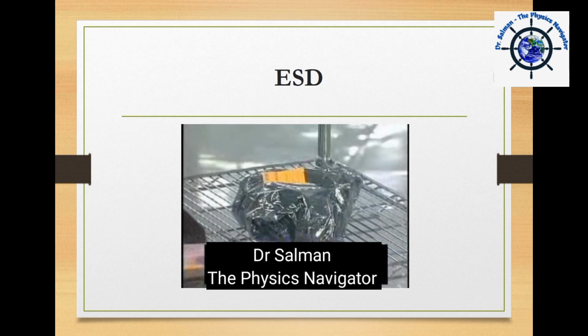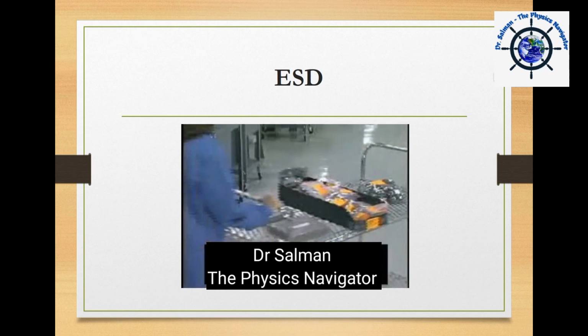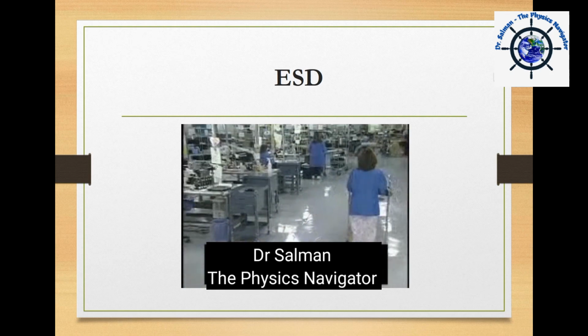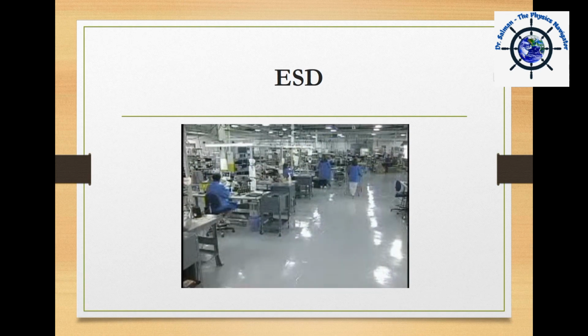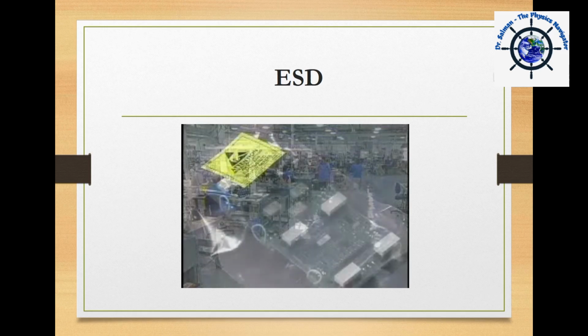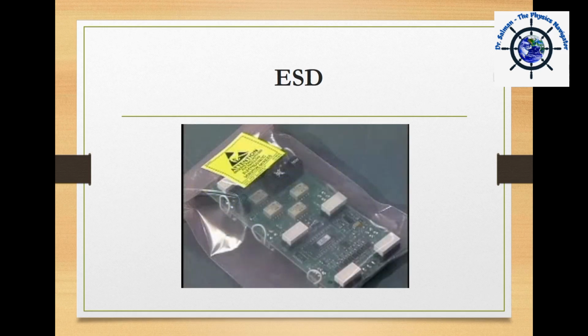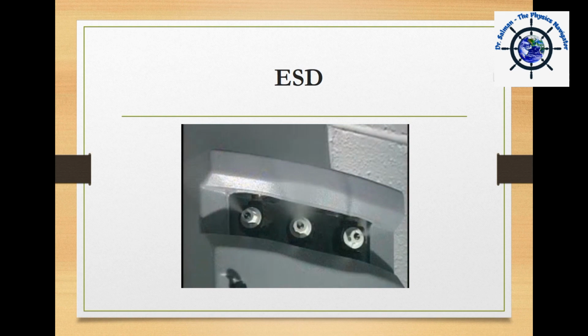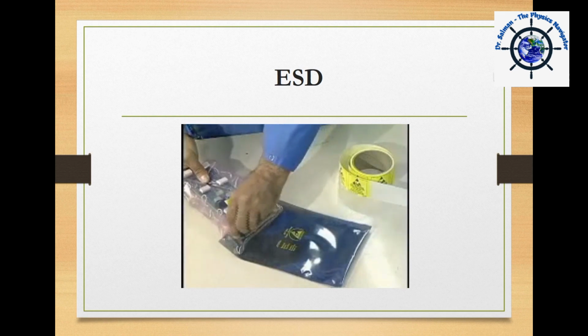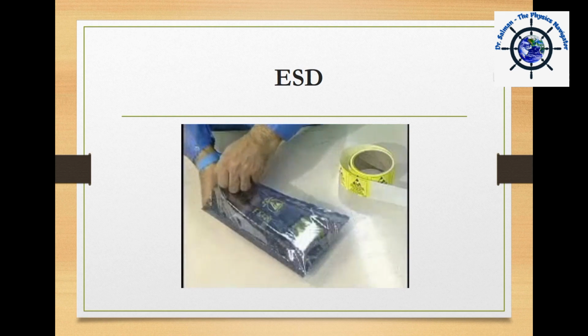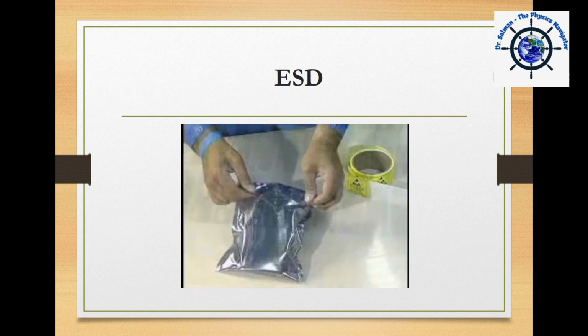All ESD-sensitive items should be stored and transported in static dissipative or static shielding containers. These special bags or boxes will provide some level of ESD protection around the device. Anti-static or pink poly packaging only serves to reduce charge generation and does not provide static shielding. These materials depend on humidity in the air and are not considered protective unless used along with static shielding packaging. The highest level of protection can be obtained by a combination of the different materials.